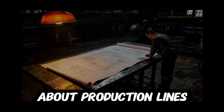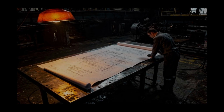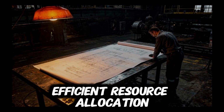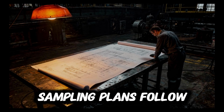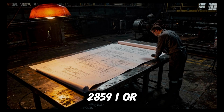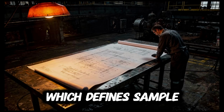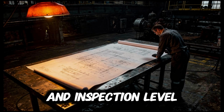What about production lines? You cannot inspect every single part manually at high speed. When inspecting production lots or large component populations, statistical sampling ensures efficient resource allocation while maintaining quality confidence. Sampling plans follow internationally recognized standards such as ISO 28591 or ANSI/ASQ Z1.4, which defines sample sizes and acceptance numbers based on lot size and inspection level.